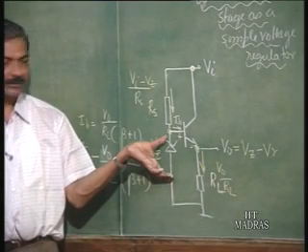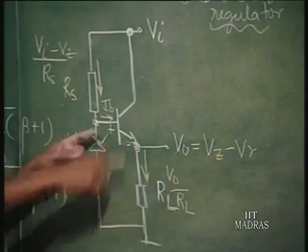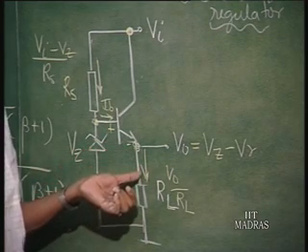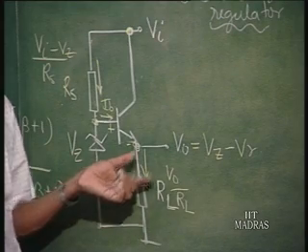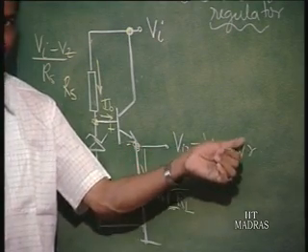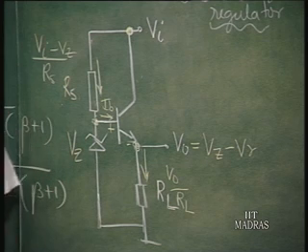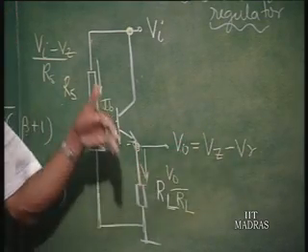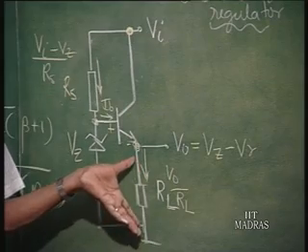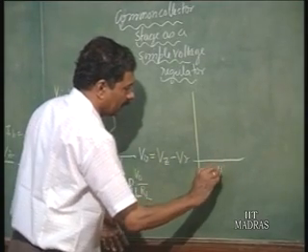That is one effect. Apart from that, V z is going to decrease, and V gamma, that is the cut in voltage of this, as the current increases, V gamma is going to increase. So, this is going to increase in magnitude, this is going to decrease. So, finally, the voltage is going to decrease. V z is going to decrease, V gamma is going to increase. So, V naught is going to decrease as we load more and more. So, you can see that this is what happens with I L.